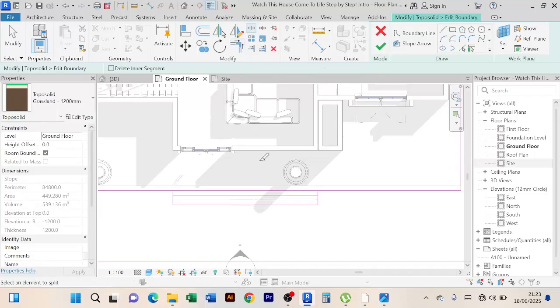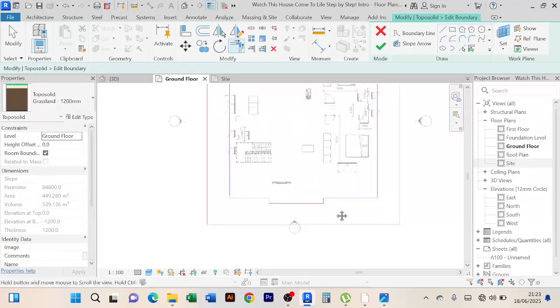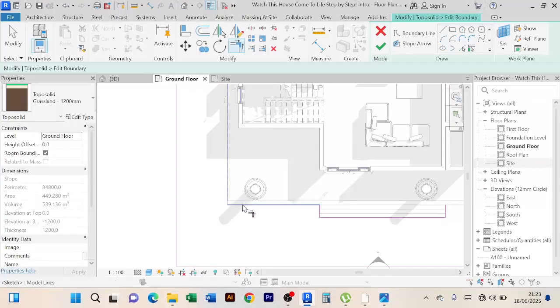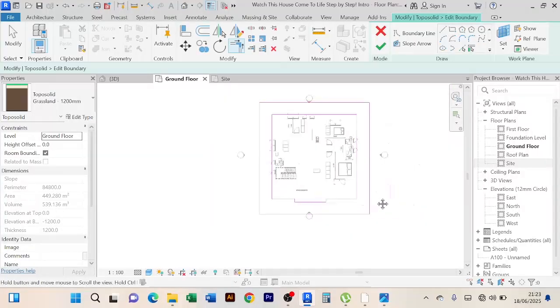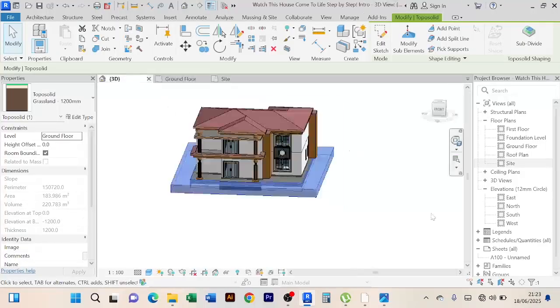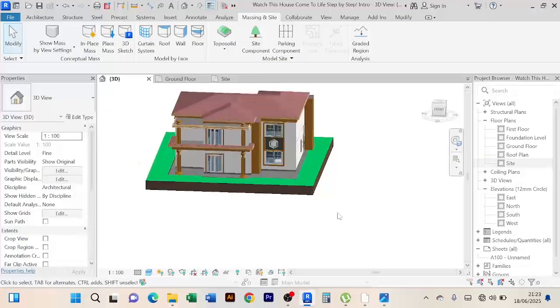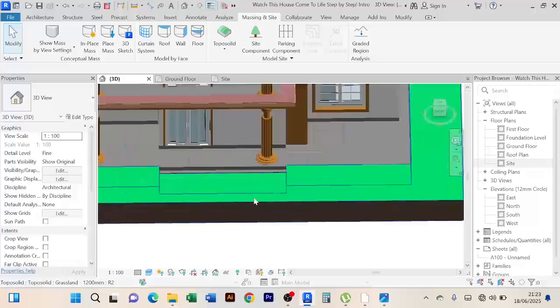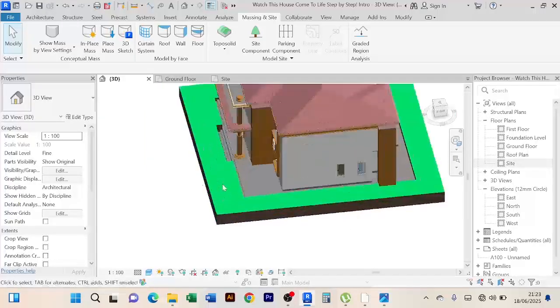We're going to click on the split tool. We shall split this, come to trim, we bring this to this, bring this to this. Then of course this part has to link up just like that. When I finish it up, you realize Revit is no longer complaining. That means we have removed the house from the toposolid.